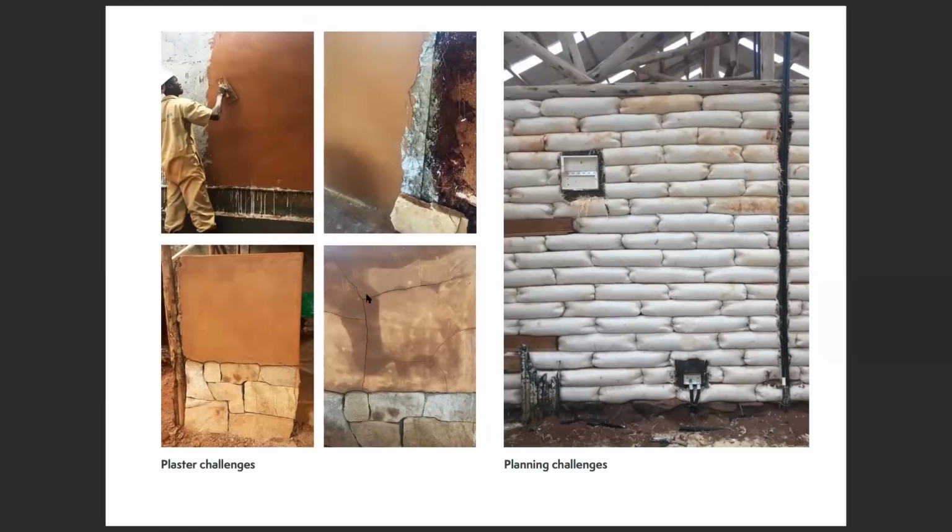This can only happen in the presence of moisture, and this reaction can even take over 6 months. But of course, it is very important early on. In the absence of moisture, that will not happen. This thing will crumble like dust. So you have to cure these walls. For us, we are trying to do it for at least 14 days.